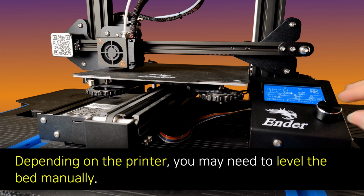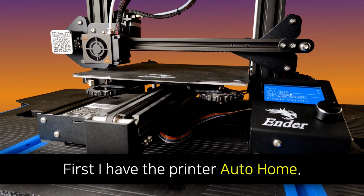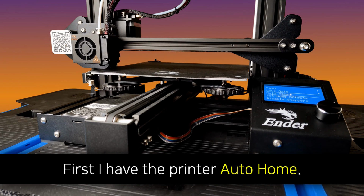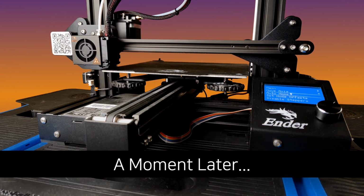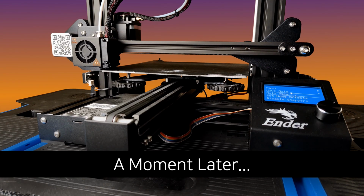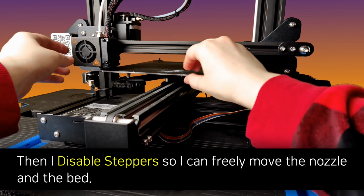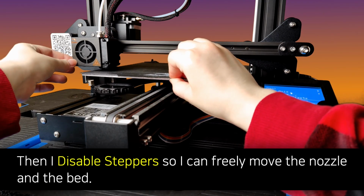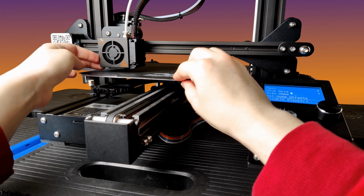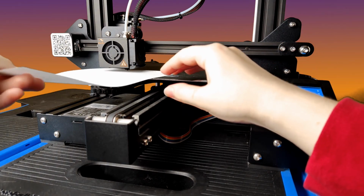Depending on the printer, you may need to level the bed manually. So for my printer, I am first having it auto home so that I can start leveling the printer. After that, I disabled the steppers so that I can move the nozzle and the bed freely without resistance. In order to level the bed, I need to turn the screws with the gears on the bottom.